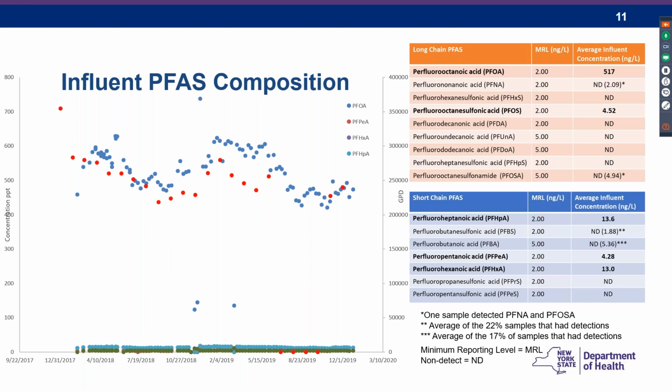And this makes sense in this particular case because the contamination is from an industrial installation, which is upstream. The wells are down in a valley. The industrial application is up on a hill. And so as they're increasing their pumping, it looks like the cone of depression is increasing, or the cone of influence is increasing, and they're getting more of that PFAS mixture.